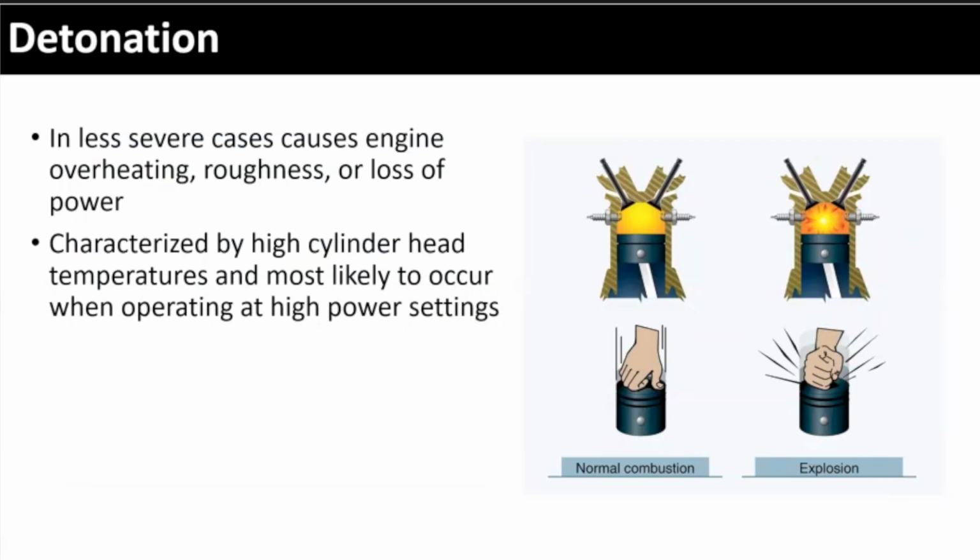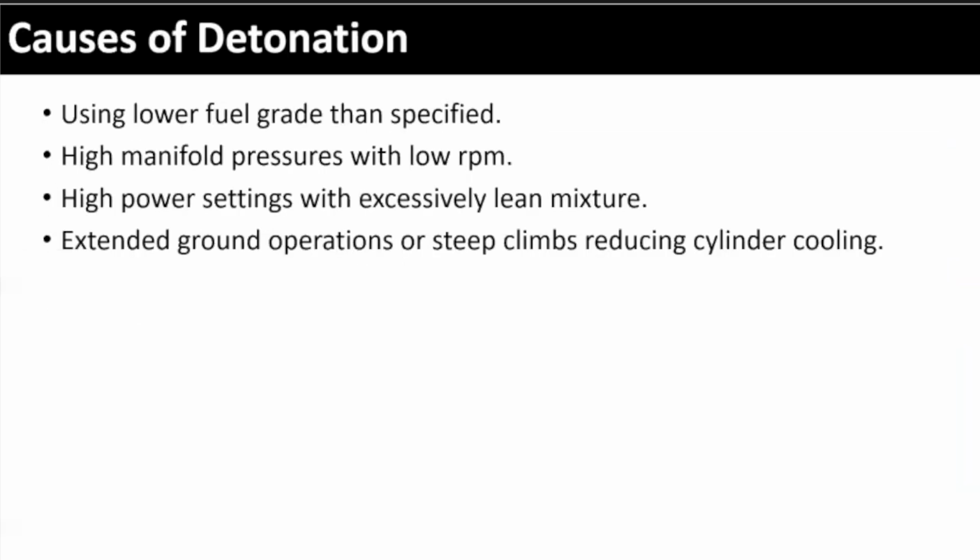High cylinder head temperatures, we're going to talk about cylinder head temperatures in a couple of slides. But if you start to see high cylinder head temperatures, meaning your engine's running hot, that's a good indication that you're going to encounter detonation, right? You need to get those engine cylinders cooled off a little bit. It's burning too hot. You can get detonation if you're using too low fuel, high manifold pressures, or high power settings with a lean mixture.